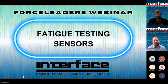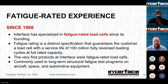All right, fatigue testing sensors. So let's start talking a little bit about specific sensors. I'll keep going on this one, Jamie. Interface, since 1968, has been offering very high precision fatigue rated solutions. Some of our earliest load cells were actually fatigue rated, given the primary markets we were serving at the time, aerospace testing, for example. But an Interface fatigue rated load cell is guaranteed for a minimum of 100 million fully reversed cycles.